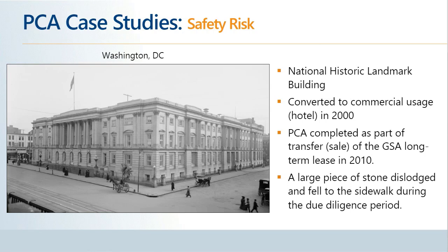The spalls, in many cases, were completely dislodged, but they were contained by bird netting that was installed at the upper cornice area, which is immediately above the column capitals. In addition to noting the spalls that were contained within the bird netting, there was also several pieces of stone material that were collected in the small setback space between the sidewalks that surround the building and the building itself.